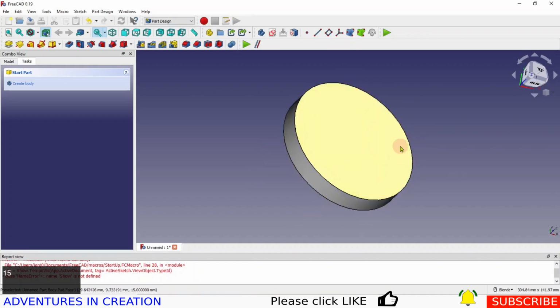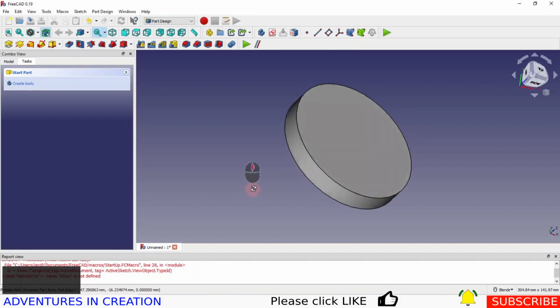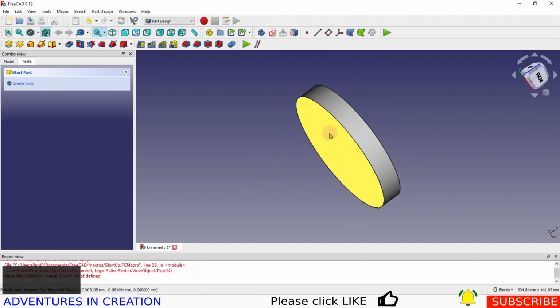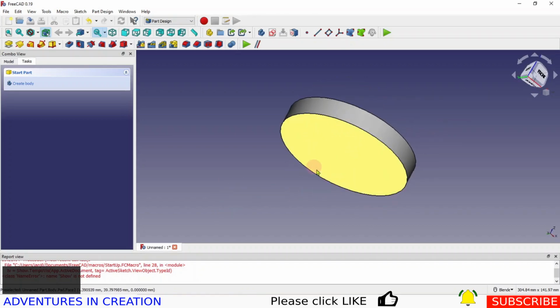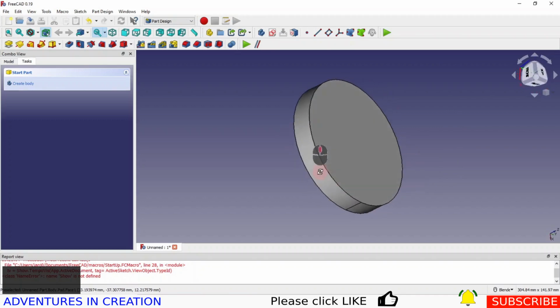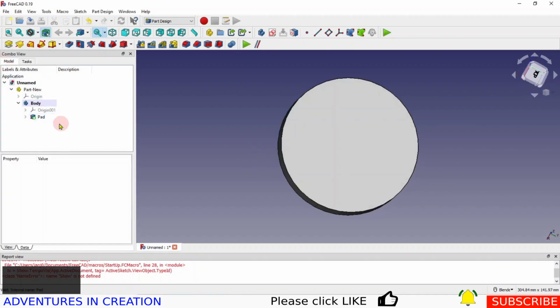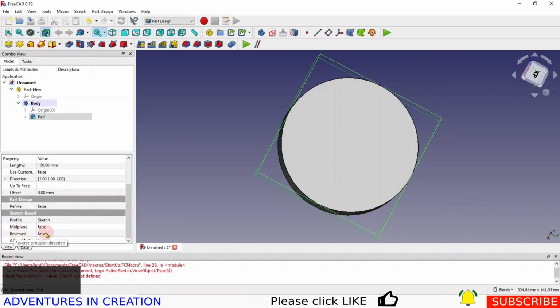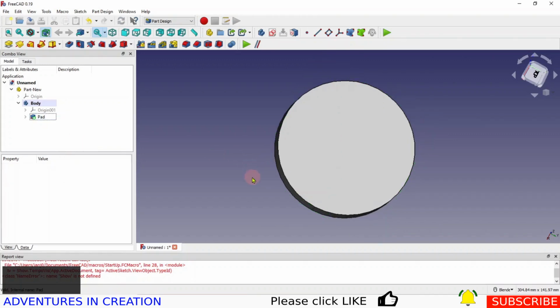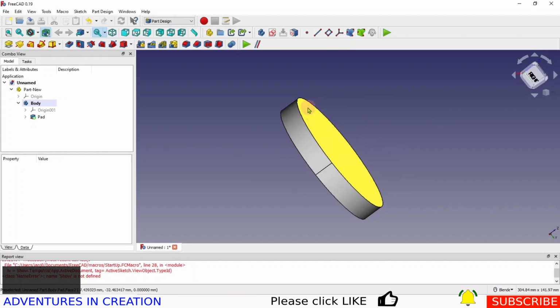Now, one thing I'm going to do, and just thinking about this, is I want to sketch now a recess in the top. Well, the plane that I sketched on is this face here. So if I sketch a recess here on the XY plane, it's going to be in the back. So to make my life very easy, I'm going to take that pad, go down here, and set reversed to true. And then when I click away from that, it's the same pad except the XY plane is sitting on the top here and the pad is going downwards.